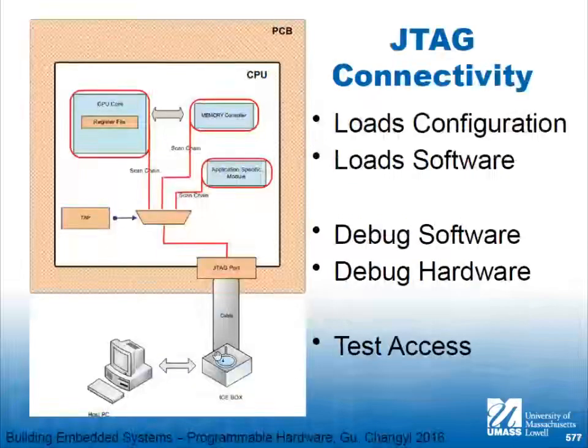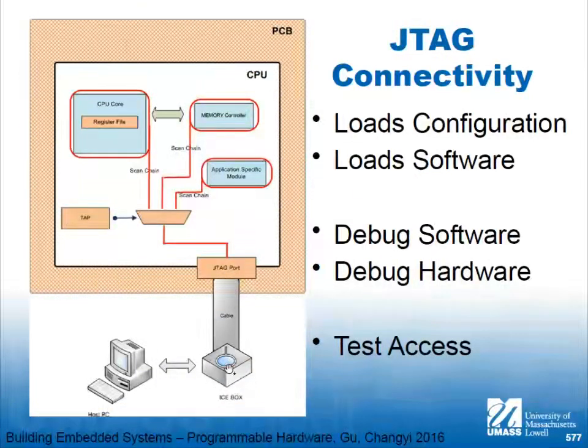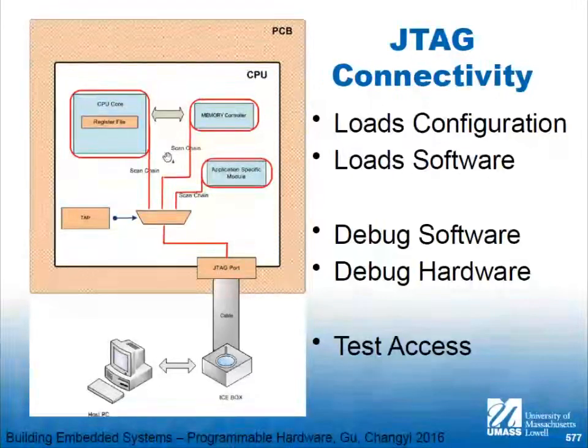All right, next. Here it is. Here's the JTAG connectivity. So I can take my PC and over what's usually a USB port, I go to this JTAG adapter. And these are anywhere from $5 on eBay to a couple $100 if they have more capability, right? And if you're using an FPGA, you use the manufacturer's device or a direct knockoff of the manufacturer's device. So that goes to a JTAG port. The JTAG port talks to your logic, it talks to your memory, and it talks to your CPU.